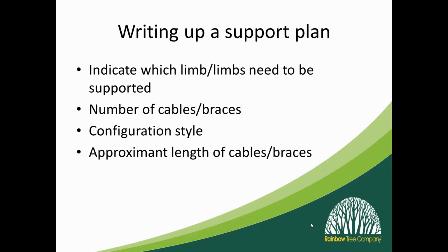An easy way to do that, once you know your configuration plan and where the cable is going to be, is to step it off. That's really helpful for knowing if we have enough cable with us, if it's 30-foot spans or 20-foot spans, so we're not running out of cable mid-job or having to lug around two rolls of cabling.